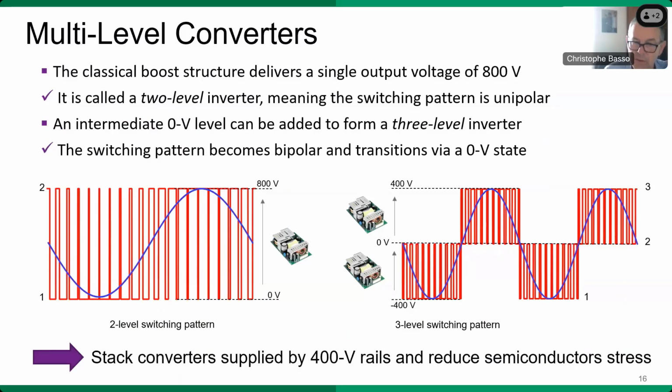In the terminology of PFC, or inverters as well, sometimes you will see a term called multi-level converters. The output voltage of a boost is selected based on the maximum peak input voltage, okay? For 265 volt RMS single phase, usually a 400 volt DC output is adopted, but some applications which operate down to 85 volts, like universal input, can dynamically set different levels to improve efficiency.